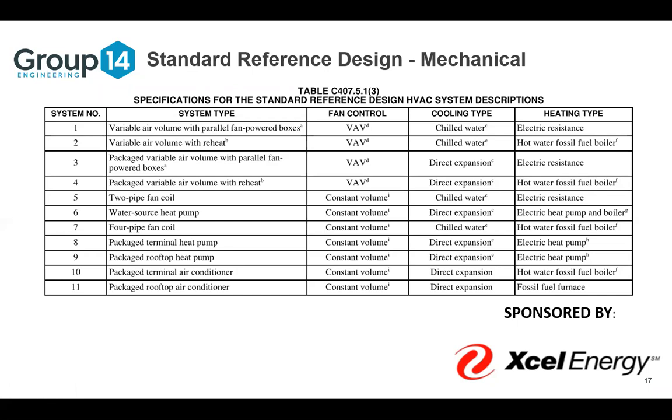notes. For example, within a VAV system, they say to allow your VAV boxes to turn down to 0.4 CFM per square foot in your baseline design. So that's increased energy over your design, which is probably a 30% turn down. So there are some things like that that are going to differ between the baseline and proposed just by the nature of those notes.